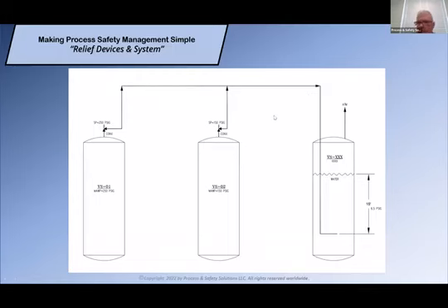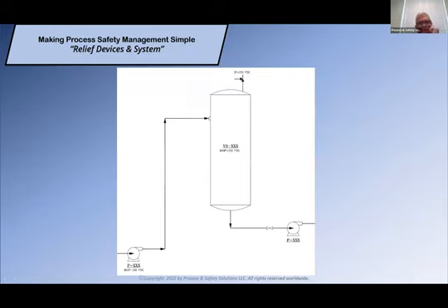The next one I want to look at is why I said it was important to make sure we document all our relief scenarios. In this particular case, I've got a relief valve here lifting at 250. The maximum pressure output of this pump is 280 PSIG. So theoretically, I could be blocked in, with no way to get out of that vessel, and this pump continues to pump.